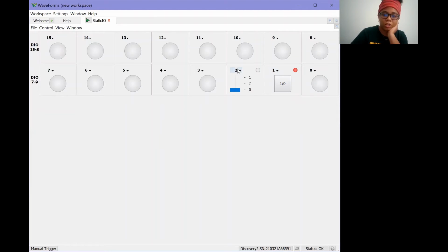And then going into the switch, we can set it to a switch, just a simple push-pull switch. So if it's 0, then the LED will turn off. If it's 1, it turns on. But because our static IO is off and I haven't connected them together yet, nothing is happening to our LED. So first thing you're going to do before you turn on any circuit is you connect your cables together.